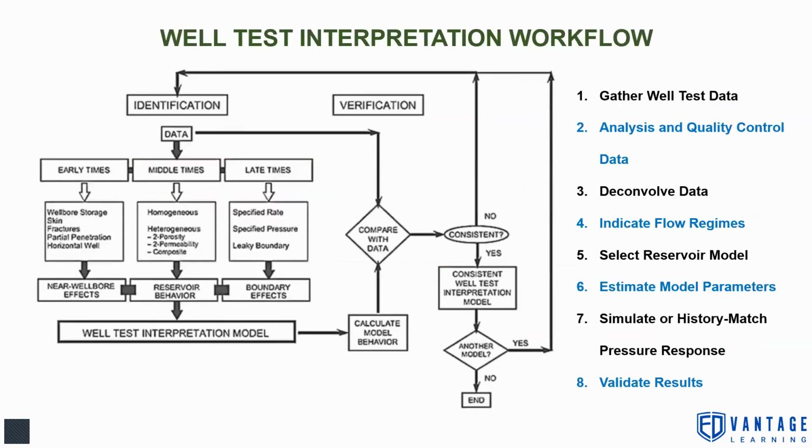So the entire workflow is to gather the well test data, analyze and quality control the data, and deconvolve the data, where we try to fix some values at the spots where we don't have data. We indicate flow regimes. We select the reservoir model. We estimate model parameters. We simulate or history match the pressure response, and we validate the results.